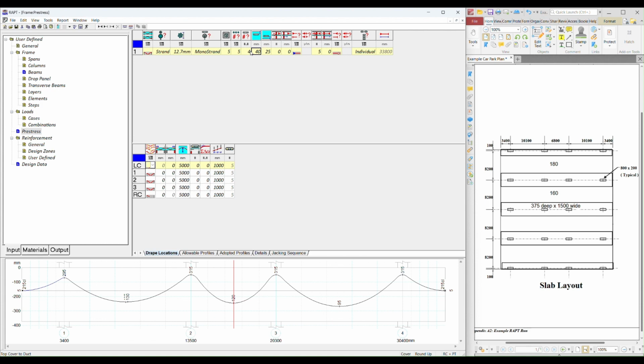However, we know that in the orthogonal direction for the slab, we don't want to clash. And so the slab will run over the top of the beam PT, and so we will ensure that the PT for the beam is set down 40 millimeters cover, and the slab will be 20 so that we don't have a clash at the high points of the columns.